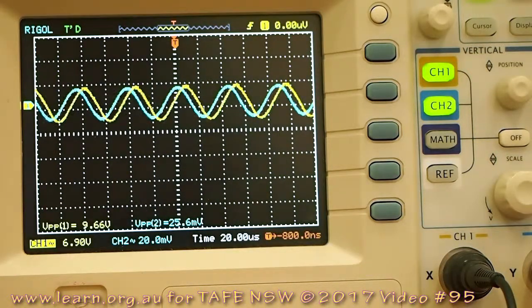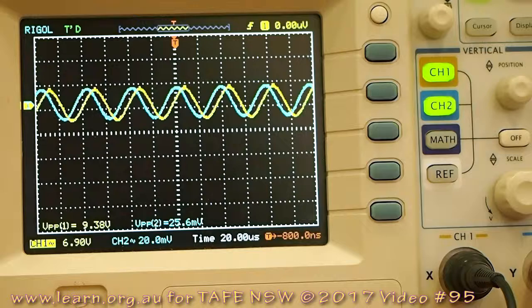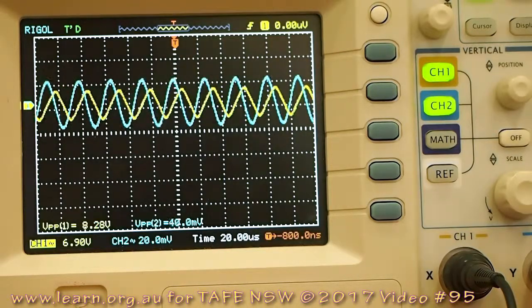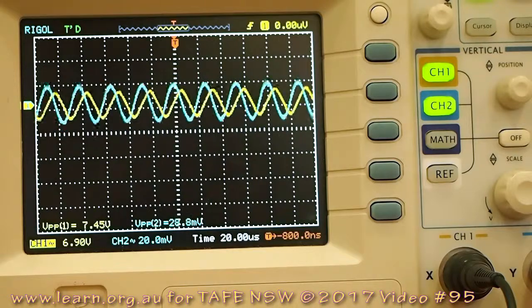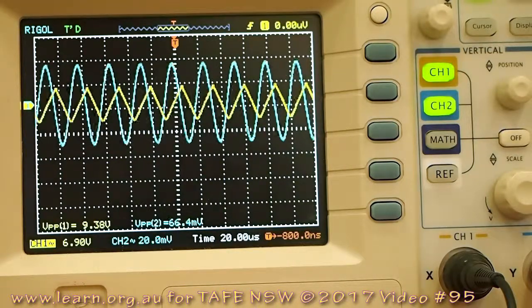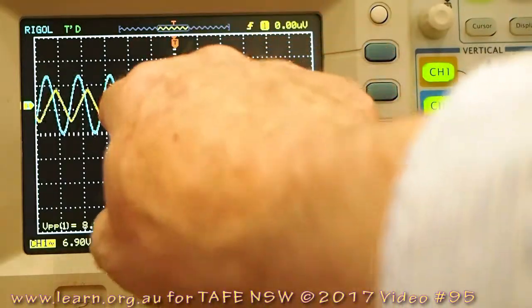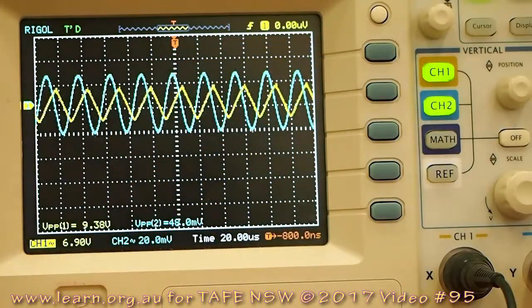Yeah, look at 23 kilohertz, I can't see any impact on that. I'll have to up the input again. Oops, no, it said I'm not going to go any further, and there you can see we've got our distortion there at 30, 36, 37 kilohertz. Quite a bit of output distortion caused by slew rate.